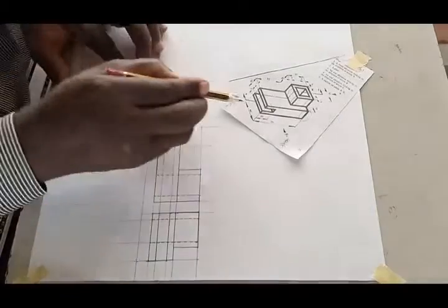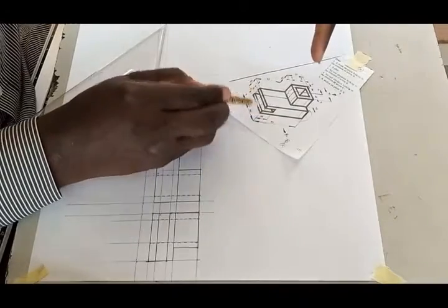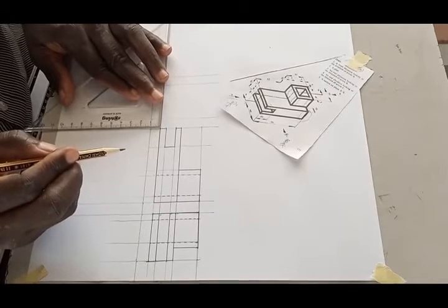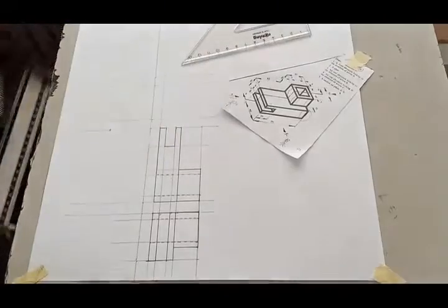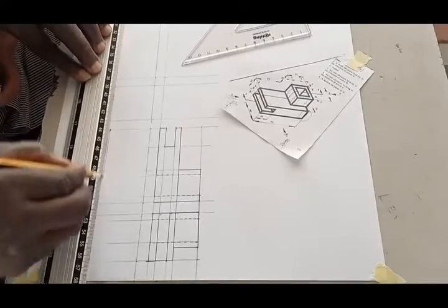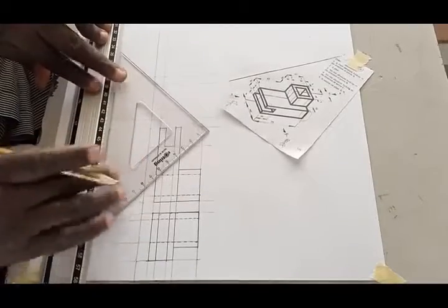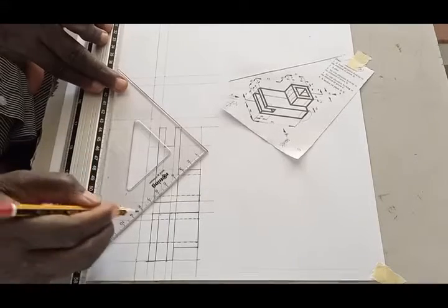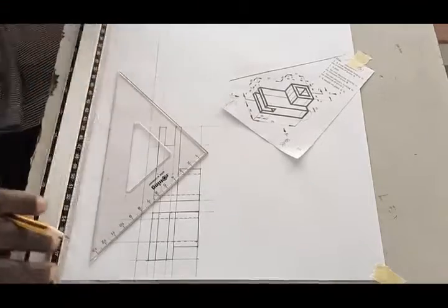So the width is from here to here. You are assuming you are looking at it from the top. So this is the total width, which is 40. So let us measure 40. 1, 2, 3, 40. And just draw it with a t-square like this. Then you measure your 45 degree. You can use this square box. Just draw the diagonal, or you put your set square to give you the same 45 degree like that.